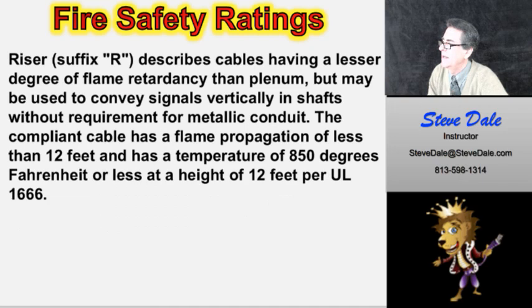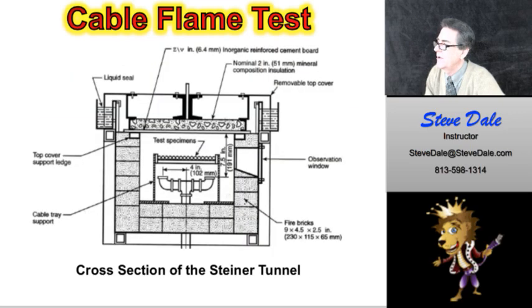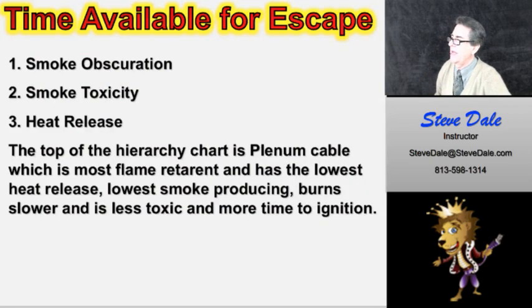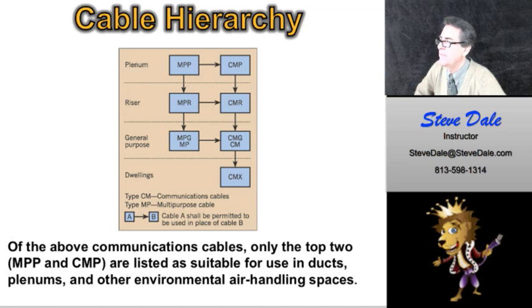So let's just jump ahead here. If you want to look quickly at the testing of these cables here, it kind of shows you how they test them. The Steiner tunnel test. Anyway, all these cables are rated based on smoke toxicity, heat release, and so forth. Okay, so here you see MPP, multi-purpose plenum cable, CMP, communication multi-purpose or communication plenum cable.